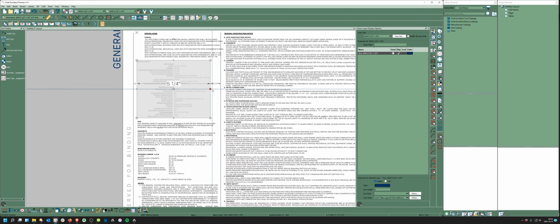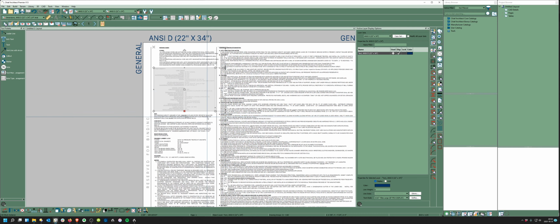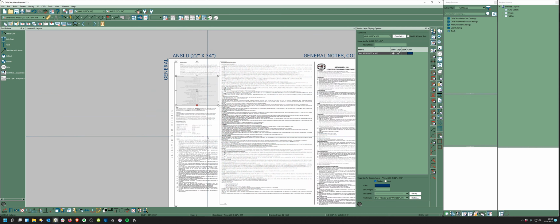And here's another trick. You can grab this handle here and drag it down and right there. So you see how that little symbol showed up? What that is, now all these are the same width, and I'm going to tell it align left edges, and then it just moved everything to line up on the left.